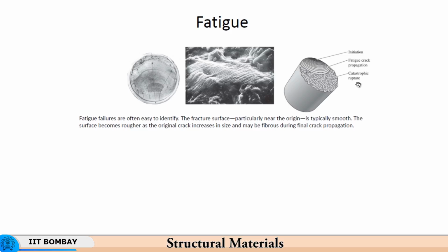So, here what you will see is that nothing would be seen from outside, because the crack is silently propagating inside with every fatigue cycle or every loading cycle, and then having advanced up to a certain extent, it will lead to a catastrophic failure. So, the consumer or the user is going to just see that the workpiece has fractured or the component has fractured all of a sudden.